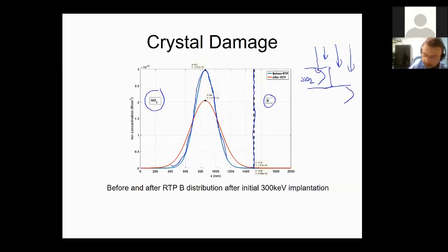Right after this, we have to put the whole thing into annealing, right? Because we'd like to repair the crystal. There's too much damage on the crystal. If we put it into the annealing process, but we do not strip the silicon dioxide away, the Gaussian distribution of the ions will also diffuse. So instead of staying confined like this, the concentration will get relaxed and will propagate. And they may propagate so much that they will start leaking under the silicon. So again, it might defeat the purpose.